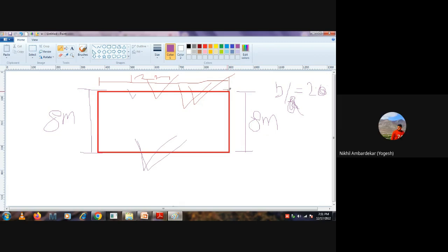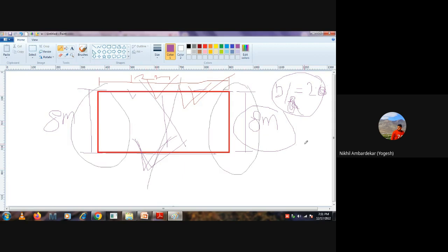So for this wall panel, you have to change only this aspect ratio. Correct? You have already calculated this, so the wall reinforcement for this wall and this wall will be the same. These are done. Now the only pending thing is this short wall. For the short wall, only your aspect ratio will change. Instead of 2.5, now you need to consider 2.